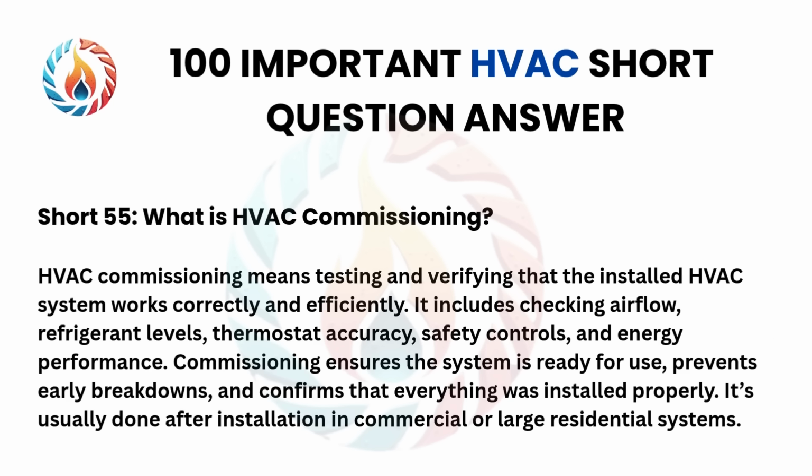Short 55. What is HVAC commissioning? HVAC commissioning means testing and verifying that the installed HVAC system works correctly and efficiently. It includes checking airflow, refrigerant levels, thermostat accuracy, safety controls, and energy performance. Commissioning ensures the system is ready for use, prevents early breakdowns, and confirms that everything was installed properly. It's usually done after installation in commercial or large residential systems.